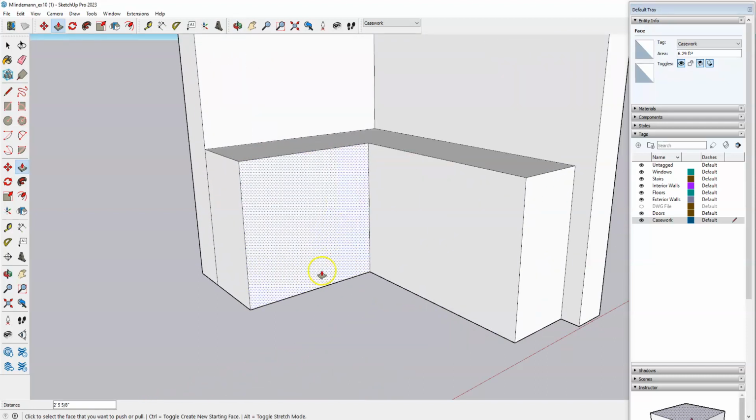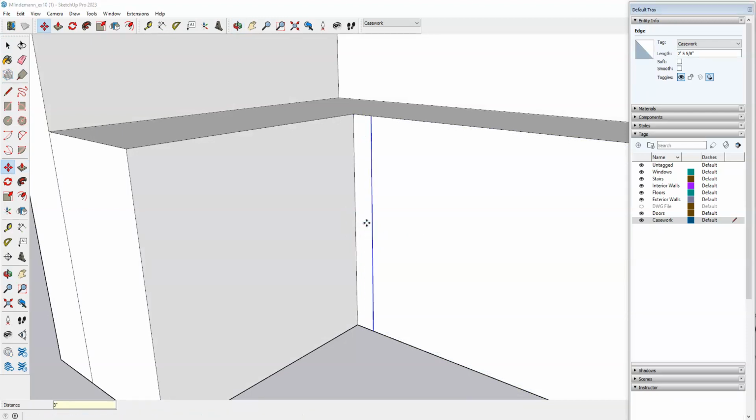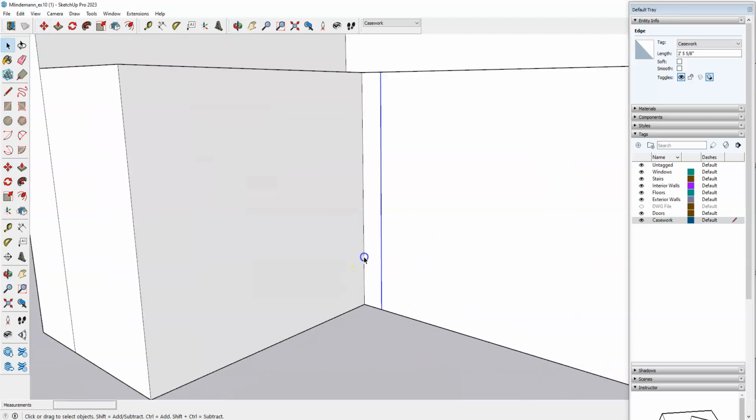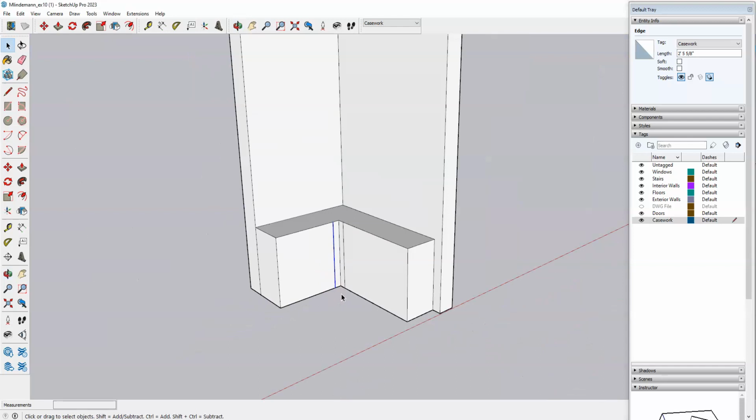If you have cabinets that are butting up against each other here, those need even more room to breathe so that they can both be open and not be interfering with each other. So if that were the case, you need at least 3 inches inside of each corner before you can start to model your cabinets, just so that both of those can open without hitting each other. And that would be true for upper cabinets as well. Does that make sense?